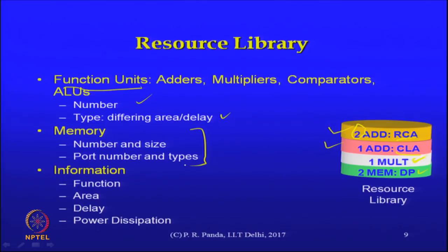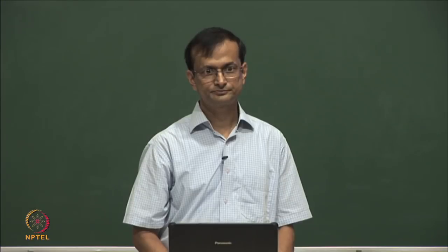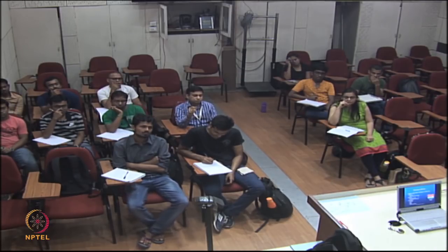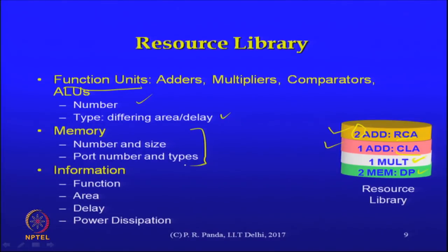Since we are doing a high level synthesis at the moment, the area and delay, which will be differing across multiple resources, would they be notional or would they be mapped to a technology? So, are the area delays technology specific? The resource library is typically technology specific. Yeah, this is still only part of the delays. Remember, there are other parts that are not necessarily visible at this time, but components are characterized for the maximum delay from any input to any output. That's the kind of information that would be available here when you pick up elements from a library.